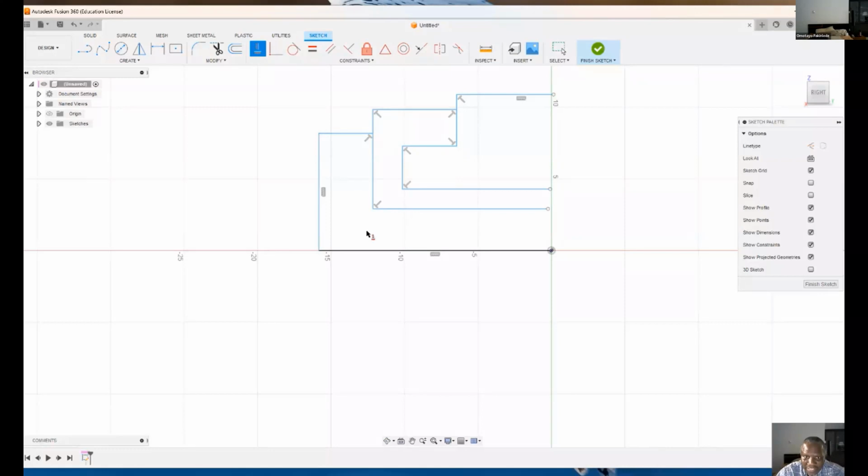If you want to insist on applying the horizontal attribute to this line, you first of all have to go away from the tool, select this right angle, and delete it. If you delete this right angle, then you can come here and apply the horizontal vertical to this, and it will work without complaining. But when you specify something that is already known to the software, it's not going to accept it, to let you know that you are over specifying.